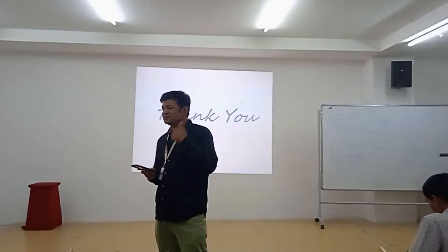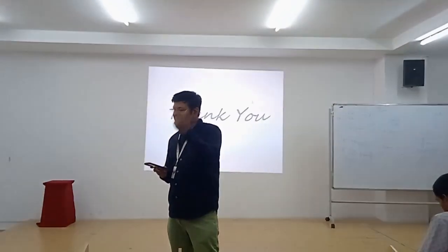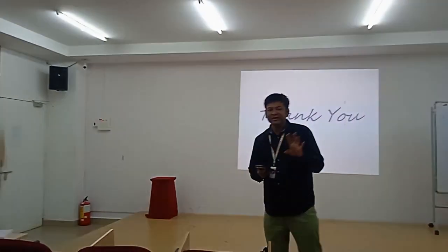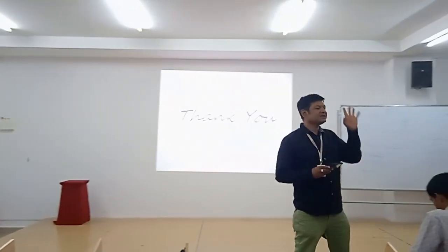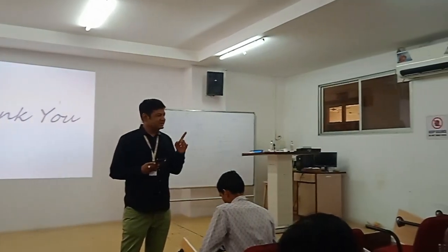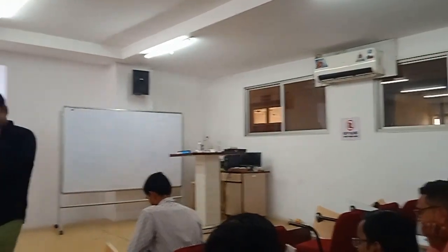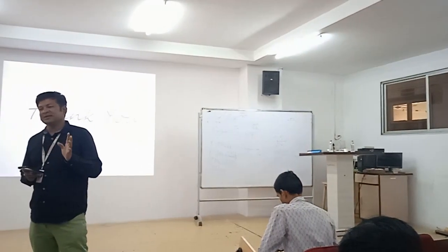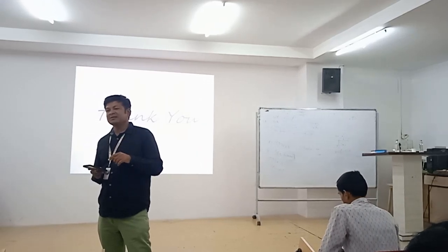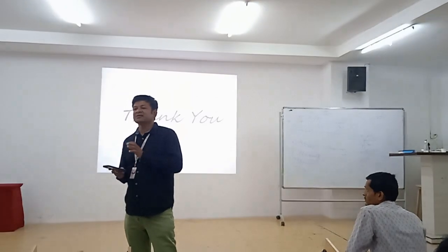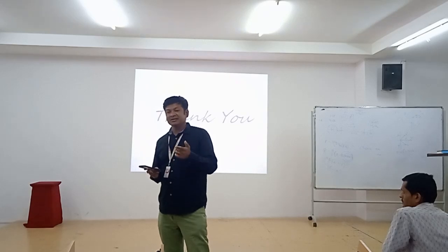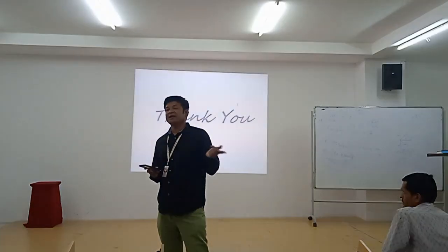The second way is you consider your system dynamics in continuous form and your measurement in discrete form. That's why it is called continuous discrete dynamics. Continuous discrete dynamical system, and that's why it is called the hybrid estimator. So we consider here the extended Kalman filter as a continuous discrete extended Kalman filter. So your measurement is discrete, whereas your system dynamics is continuous.